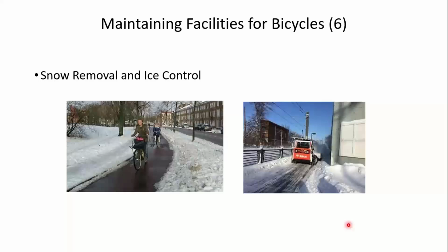You do not have to touch the sidewalk, say mid-block, but that obstacle, whether it's a heaved up sidewalk slab or maybe it's a big hole in the sidewalk that makes it inaccessible, that barrier needs to be on the agency's transition plan to demonstrate that they're aware of that barrier to mobility and they know what needs to be done to correct it. And of course, a transition plan also includes a schedule of when you're going to correct it. So that was a long answer, but I'd be glad to answer additional questions on that.